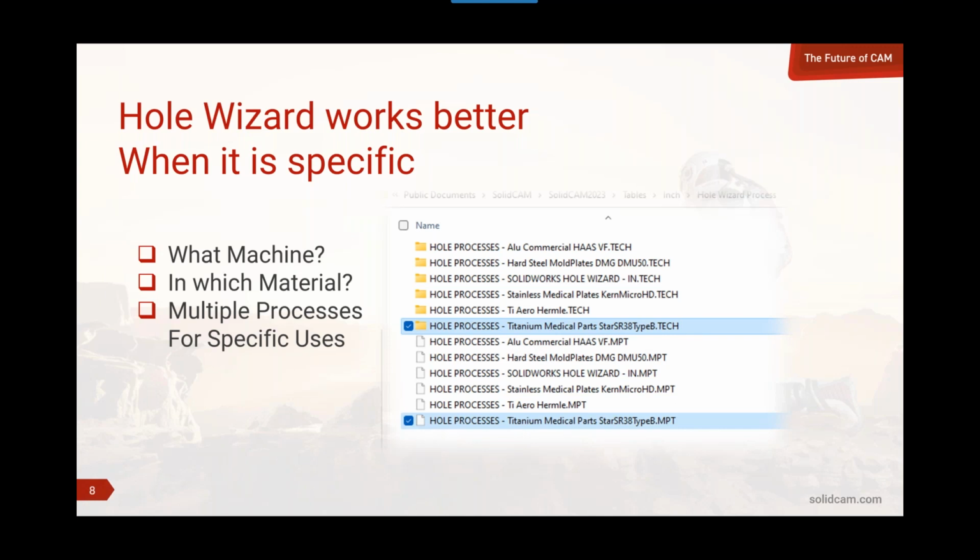For the most part, if I'm not tightly toleranced and I'm only putting it into aluminum, I can pull the drill size that I want and go plug a hole in the plate. Not a big deal. If I'm working with hard steel mold plates, I might need a few different procedures to go in there. If the mold is on a cavity side, I might want to circle mill a flat position for the spot drill to hit before I do anything else. If it's on a flat plate, I might want to run the spot drill before I do anything else.